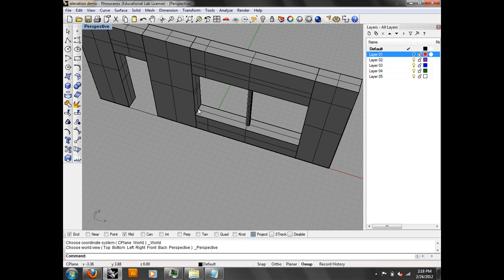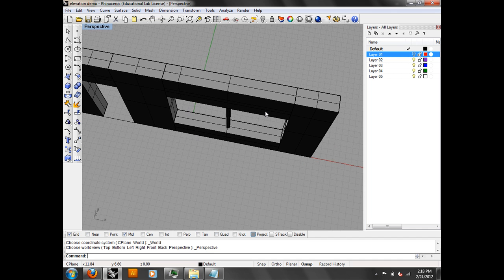Question? Regarding the structure, if you do see it in the exterior elevation, but you're not meant to see it on the interior? You model the parts you see. That's actually a good rule of thumb for anything in the model. If you are never going to go inside of a building and you're never going to see inside of it, don't model the inside of the building, just model the outside of the building. Again, it's not a one-to-one model of your building. You're modeling the stuff that you want to see. You're modeling the stuff that you're going to draw.